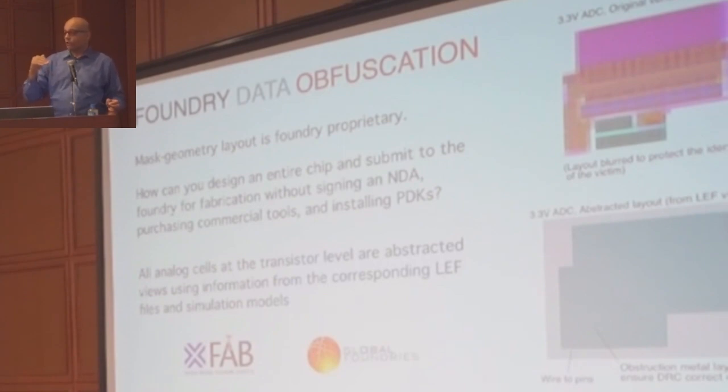You can use processes or PDKs that are not open source from specific foundries in the specialty space, mostly targeted towards heavy analog mixed signal, like XFAB. When we obfuscate the PDK, we hide certain pieces of it that don't impact how the designer works. So you can, for example, with a foundry like XFAB, where we agreed that we're going to hide the baseline and leave the back end, all the metal up, possibly open for these products.